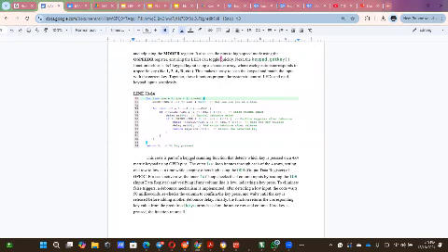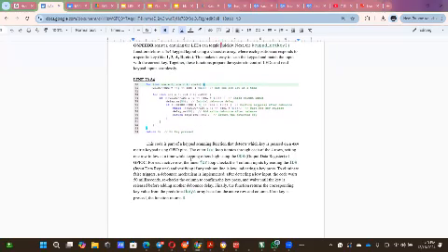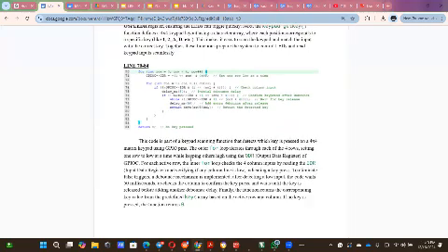Alright, so next for line 70 to 84, as you can see in the picture, this code is part of a keypad scanning function that detects which key is pressed on a 4 times 4 matrix keypad using GPIO pins. The outer for loop iterates through each of the four rows, setting one row to low at a time while keeping others high using ODR, otherwise known as Output Data Register of GPIO-C.